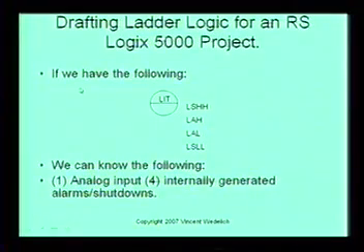And again, here if we had the following: a level indicating transmitter, LSHH, LAH, LAL, LSLL. Now here, S right here means shutdown. So we have level shutdown high-high, level alarm high, and level shutdown low-low. If we have a level shutdown, we actually stop the process. We close the valve, we stop the pump, we close the modulating valve, we shut things down.